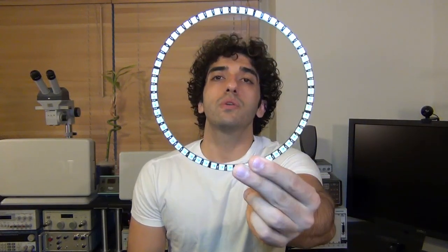So what we're going to do is program this using C, using a PIC, basically straight up using a very simple circuit. And also we're going to measure the waveform and talk about some of the challenges that go into programming these using C as opposed to assembly, which I believe the optimized libraries for Arduino internally actually do, because it's very hard to meet the timing requirements of these things with a low crystal oscillator microcontroller right off the bat.